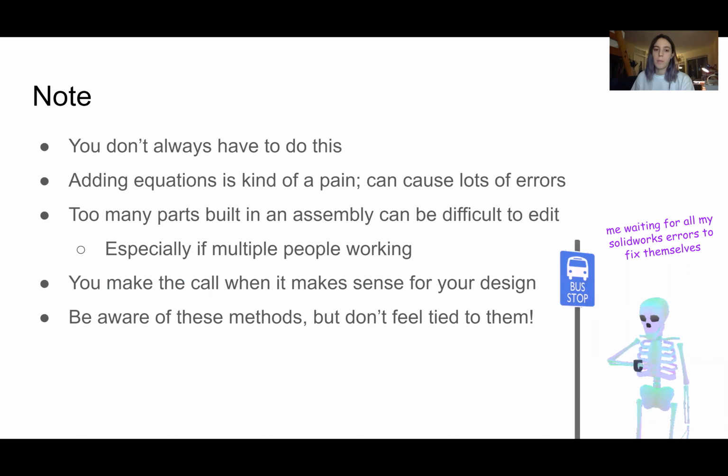It takes a lot of time to add in the equations. If there's a lot of parts in your assembly and you're editing them all in context, it'll slow it down because it has to load all of those different files. And if you're working with a team, which we mentioned earlier, it is even more difficult. So it really requires a lot of communication.